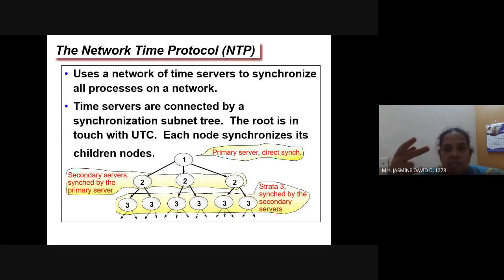They have classified the noise into two types: phase noise and frequency noise. Some of the causes of phase noise are access fluctuations at the hardware interface, response variation of the operating system to interrupts, and jitter in the network delay. And frequency noise is due to the instability in the clock crystal. The low-end crystal may experience large frequency fluctuations. So this is about the noise: there are two types, phase noise and frequency noise.